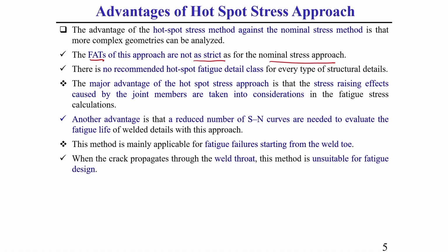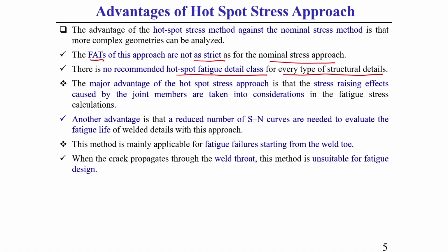There is no recommended hotspot fatigue detail class for every type of structural detail, and that is not required also. There are some standard FAT classes mainly used for this hotspot approach. According to IIW and Eurocode, presently 7 different categories of FAT class are used for the hotspot approach. Earlier only 2 FAT classes were used. What those 7 different FAT classes are, I will discuss later.